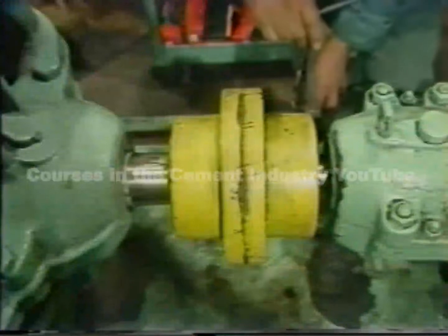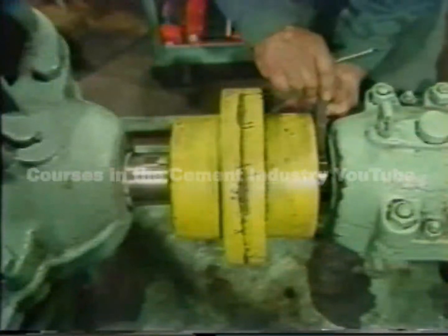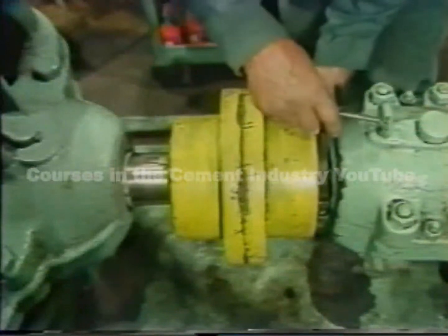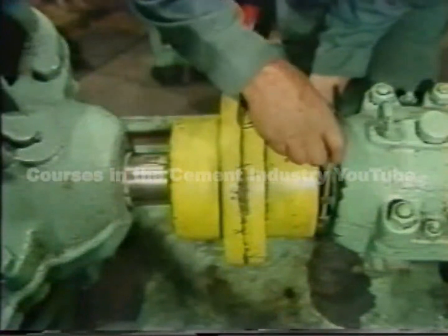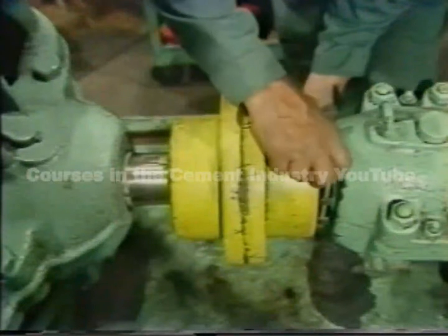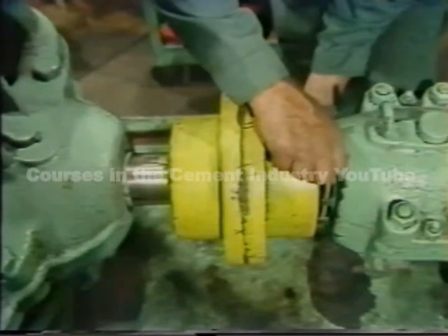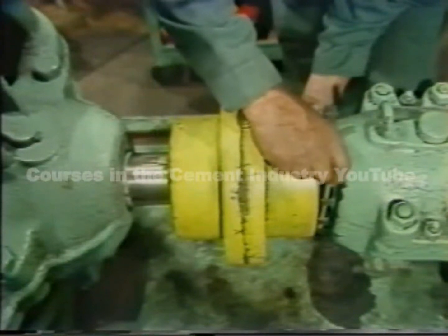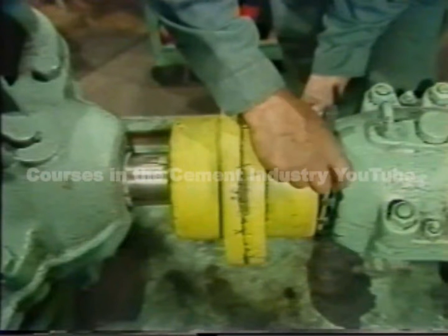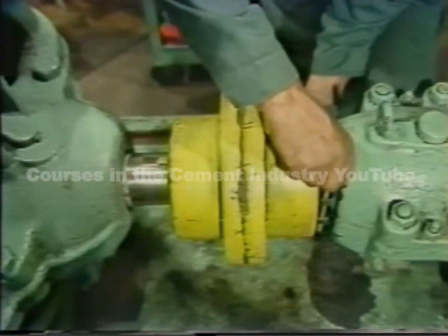The alignment rig is installed on the actual machine pretty much the same way it was installed on the pipe for the sag check. The first piece to go on is the post. The post is mounted on the pump shaft because in this case the pump shaft cannot be repositioned. The motor is much easier to move around, so we'll be aligning the motor to the pump.